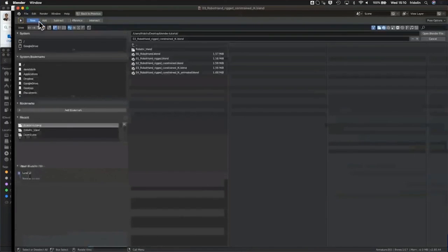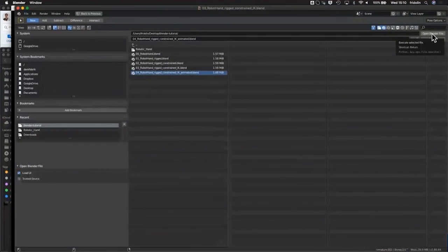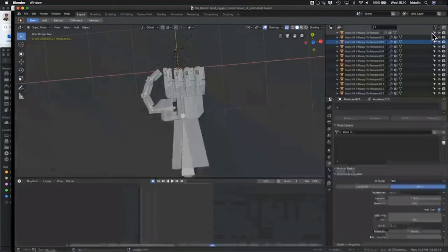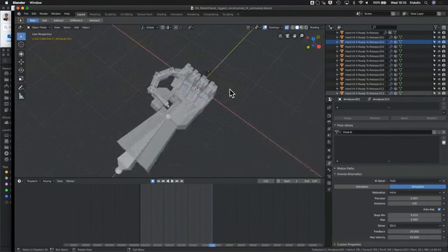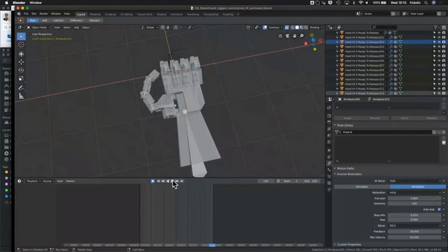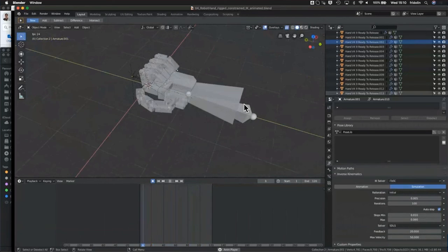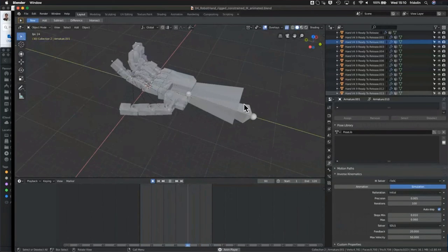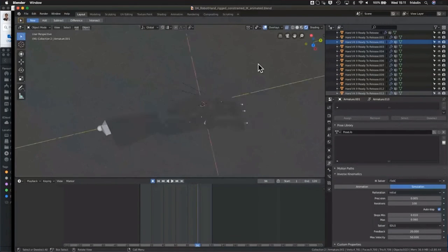So I'm going to open the final file now where I've rigged the hand, I've applied constraints to it so they move realistically within limits. I've applied inverse kinematics so that just moving the endpoint affects the entire mechanical chain leading up to it. And then I've used keyframes to save a bunch of different movements and poses. And so now we get this hand that moves through a range of different poses, like so. And we can put that into render mode, and we can give it a nice metallic material, but I don't think we'll have time for that.